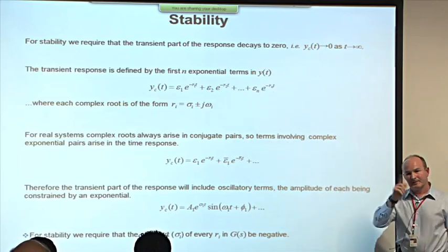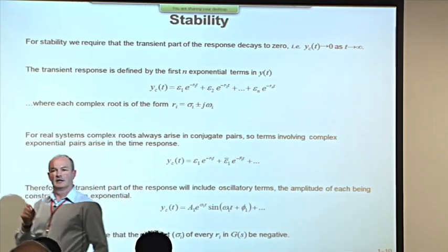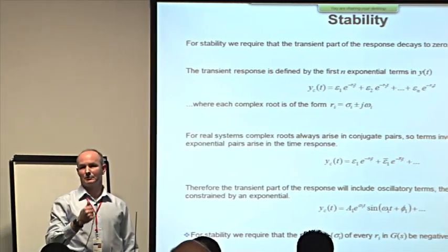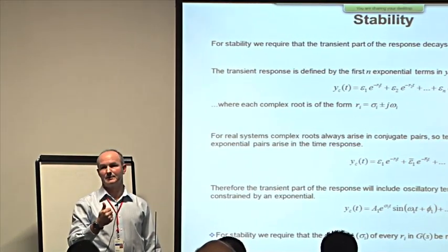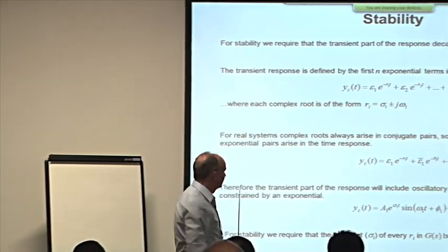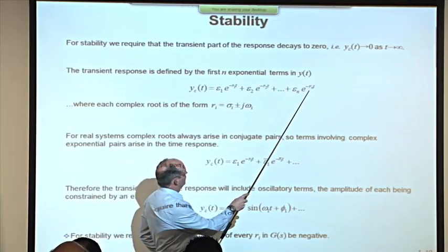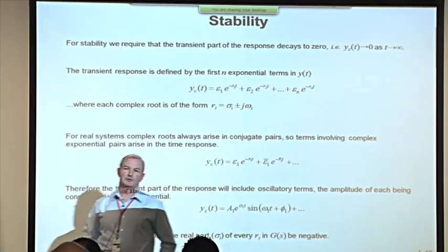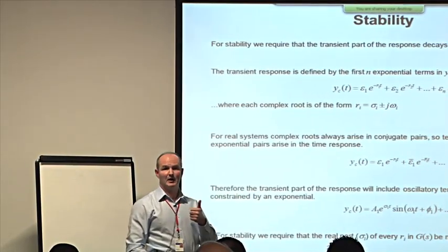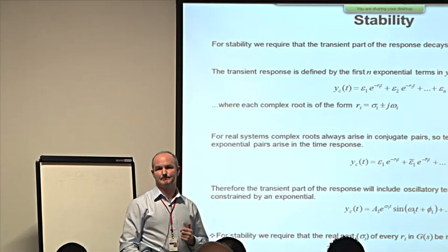Now, remember before when I said that the coefficients in that differential equation, if it's a physical system model that we're using, must all be real. They may not be constant, but they must all be real. And here's the thing about that: when you find out where these poles are, because those coefficients were real, there's only two possibilities for those poles. They'll either be real, or if they're complex, they'll exist in complex conjugate pairs.